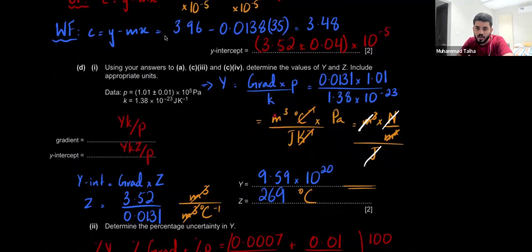And then if I just think about these units, there's a meter cube here. I can't obviously simplify this further. And pressure is force over area. So Newton over meter square, right? So with that, I see the meters also cancel out with a Newton meter here and a joule on the bottom. So Newton meter is just the unit for work, right? So joules over joules, they cancel out, and this has no units at all, right?